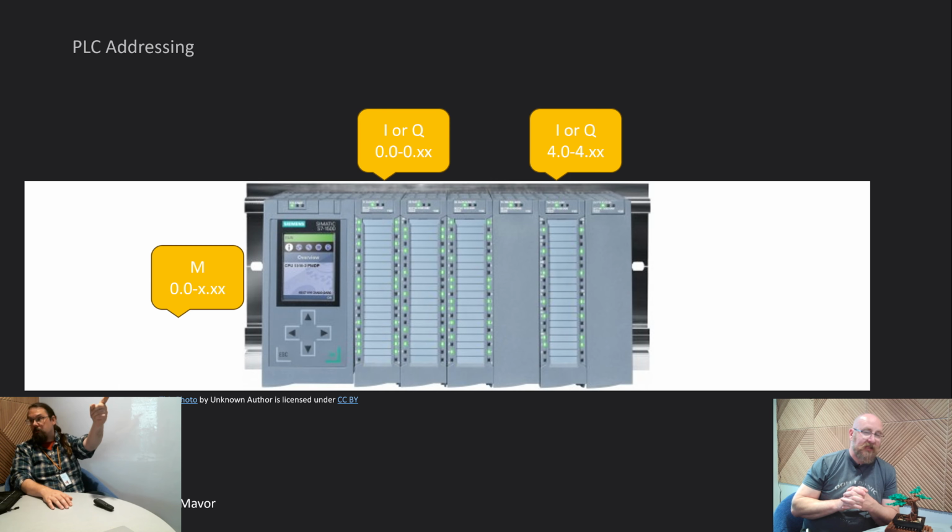Yeah, so you can use the software to help drive you when you're creating these in a thoughtful way for your tag table. Yep. That's a big thing, because if you create them in order, then they will auto-generate the next block of resources that is needed. Yeah. So you don't need to worry about conflicting addresses, but you'll get all kinds of red flags if you start creating ones that are over the top of another.